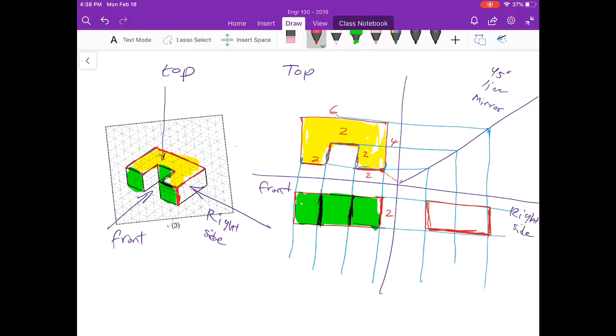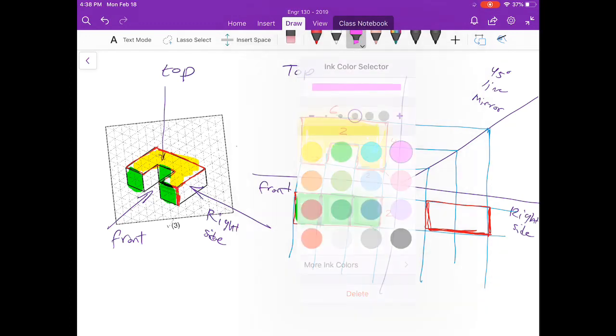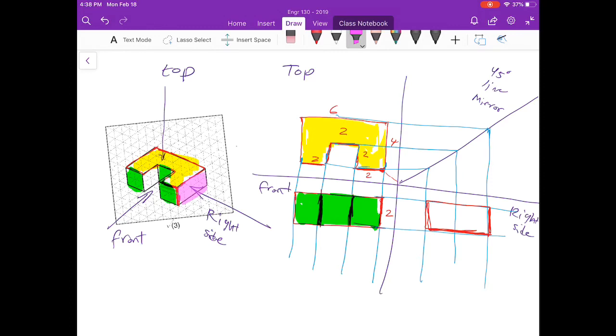But if you're looking from right side, I'm gonna purple highlight it. So this is what we can see from right side, and then this comes to here. But the issue is that if I look from right side, some areas down here are missing. When some areas over there are missing, we call it a hidden line. When you'd like to represent a hidden line, you're going to use a dashed line. So I'm going to put a dashed line here.